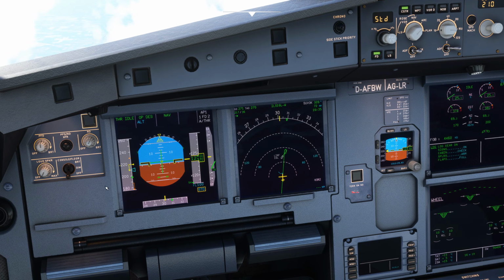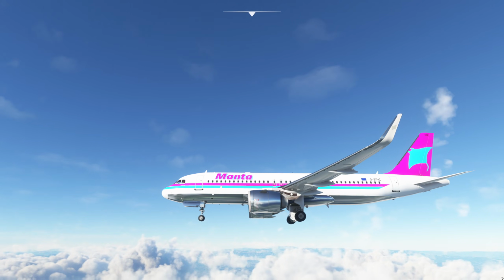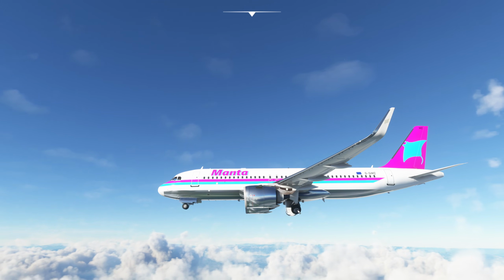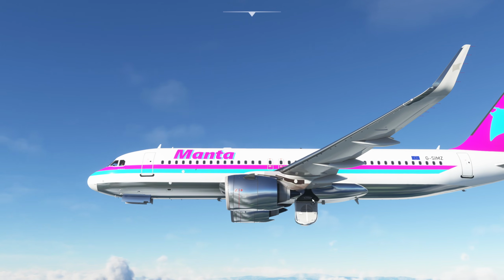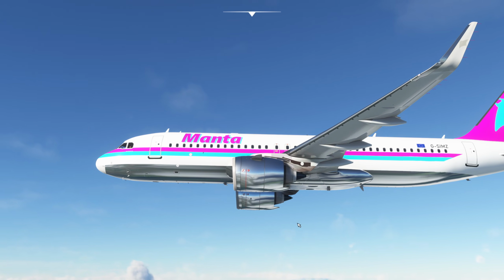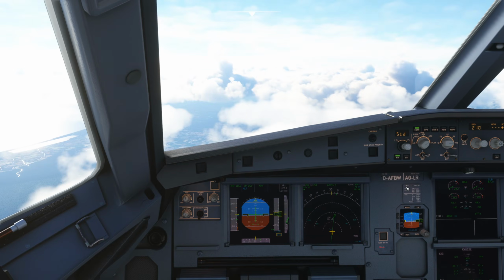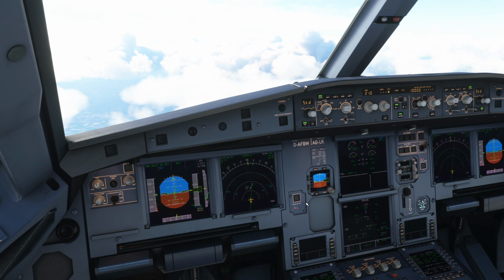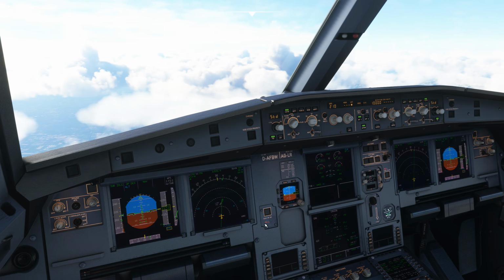So speed now below 220 knots, gear up. So notice the sequence, gear comes in. Once the gear is all locked, the doors can then close. The aircraft is very careful about the sequence on the landing gear. It does not want to get it wrong. There have been many incidents of aircraft landing without landing gear or with one of them stuck because of things that get loose or jammed. So the sequence is very carefully controlled and monitored for that exact reason, because obviously landing gear is a very useful thing to have working.